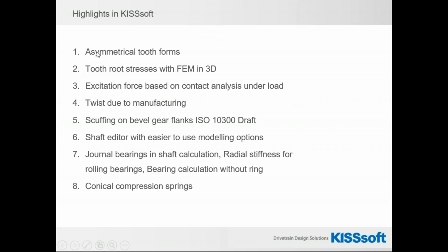First of all, one of the main highlights is the possibility to calculate asymmetric tooth forms. Let's say also quite a new topic in the industry. And in addition to that, we have an additional module to calculate 3D root stresses with the help of our internal finite element method calculation tool, Salome. Maybe you've already seen it or heard it before. In the contact analysis, we have the option to calculate, in addition to the transmission error, now also the excitation force for the evaluation of gear noise.